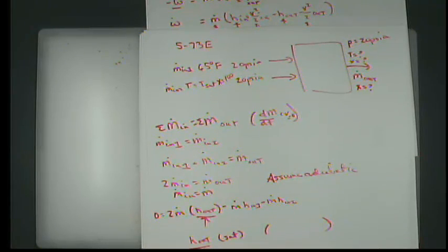That's exactly correct. Because if we're talking about steam, because here we have some sort of hot water, and what we're doing is we're mixing it with steam in order to put it into the two-phase region. That means that in here we have to be between steam and hot water. You know, we're going to be somewhere in that continuum. So if this mixes fully, if we have two-phase, it has to exist at the same temperature, doesn't it? Or same pressure, doesn't it? It's just not possible for it to exist any other way. Still don't like it. But anyway, I started doing it because I wanted English units on it, and maybe I should have gone to an SI problem. But it's okay, it's okay.